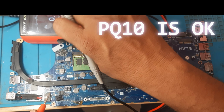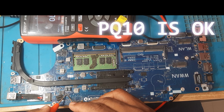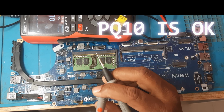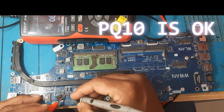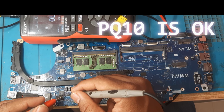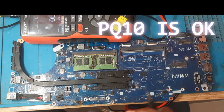Okay, one minute. Actually here, pin number 1 and 4 are ground, that's why it's giving a beep. Just a minute, I'll check once again. Pin number 1 and 4 are the ground, correct. This one is correct. Other than that the logic is good. Pin number 2, 3 there is no ground, 6, 5 also no ground. Only pin number 4 and pin number 1 are the ground. This one is okay, but what voltage we are getting, that we will check.